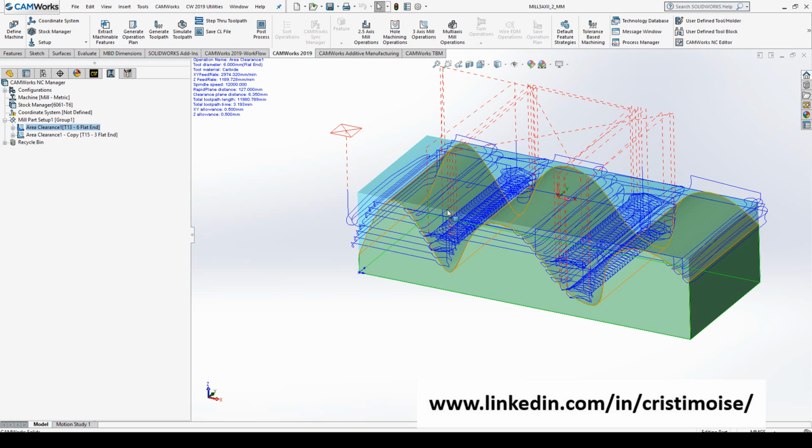This is the operation, and if you do not check it, you will have a new variable in the post processor which is called allow long code drilling cycle, which you have to set to true, and you will have long code point-to-point operation generated in CAMWorks. In some cases some users might find it useful.